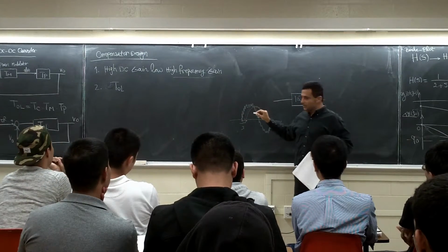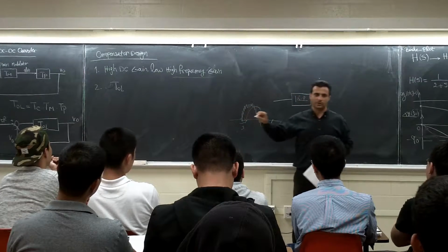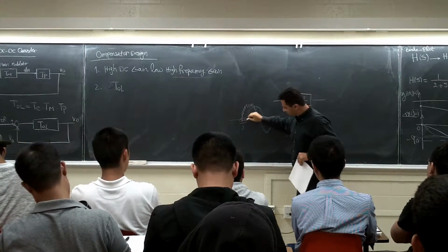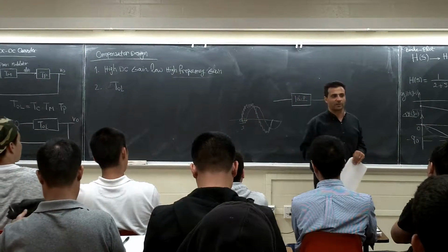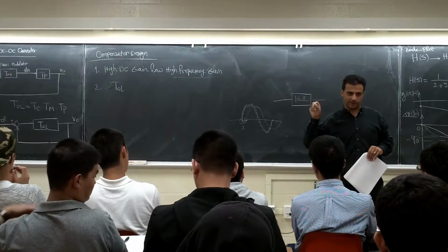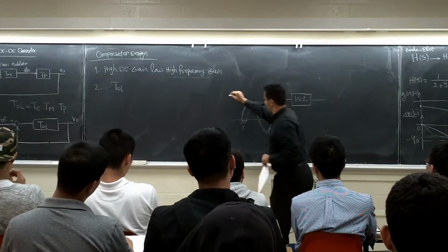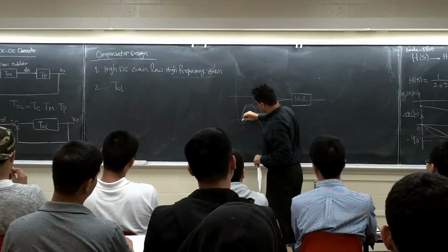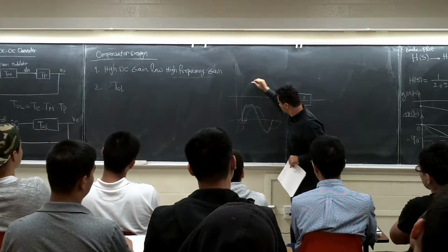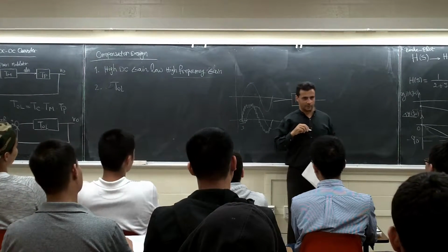I have a paper I can show you, from somebody else, not me. This little thing is causing lots of problems. They call it zero cross effect. When you cannot find the zero cross accurately, it's going to cause a problem in the current waveform. If you look at the current waveform, let's say for unity power factor, you're expecting to see something like this, right?